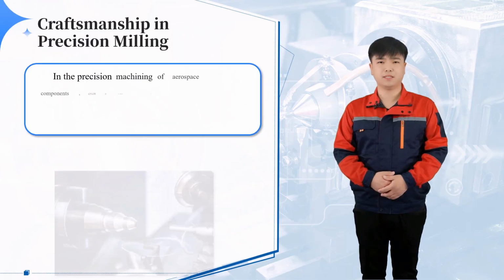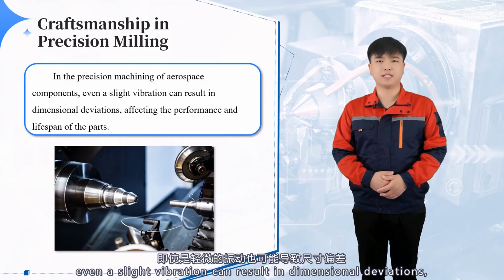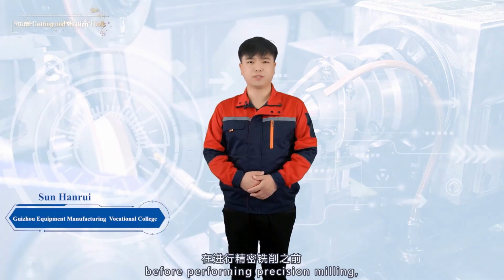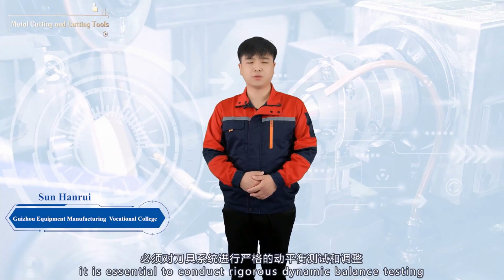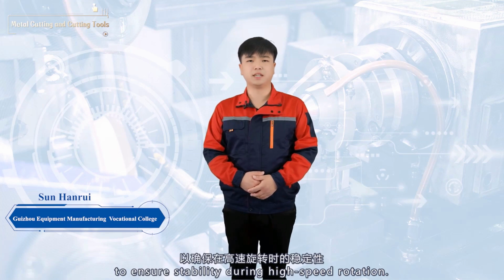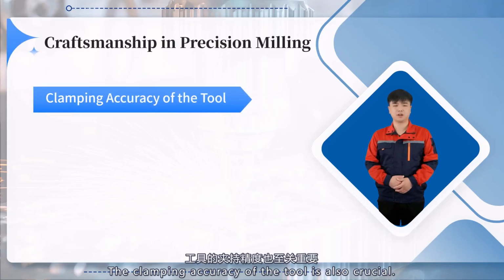For example, in the precision machining of aerospace components, even a slight vibration can result in dimensional deviations, affecting the performance and the lifespan of the parts. Therefore, before performing precision milling, it is essential to conduct rigorous dynamic balance testing and adjustments on the tool system to ensure stability during high-speed rotation. The clamping accuracy of the tool is also crucial.